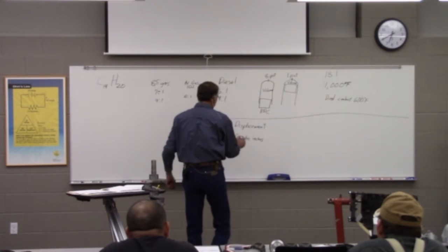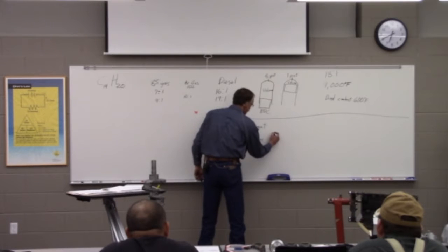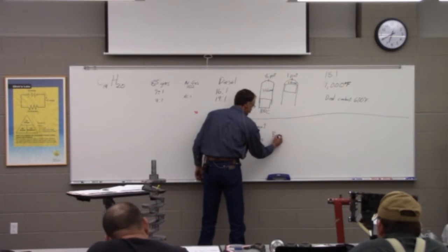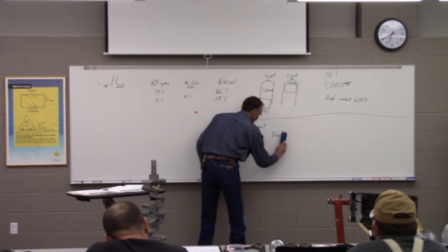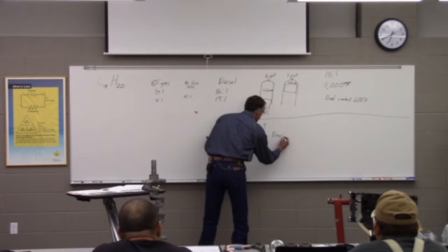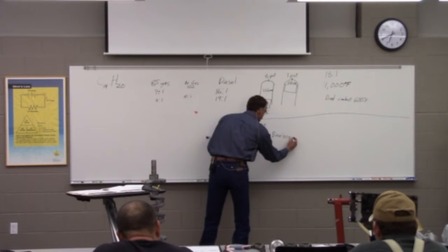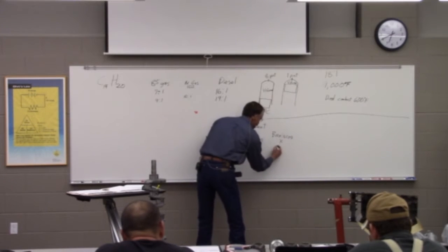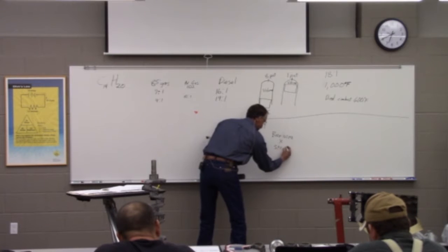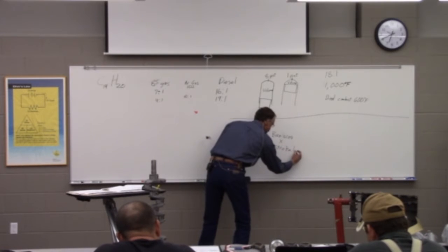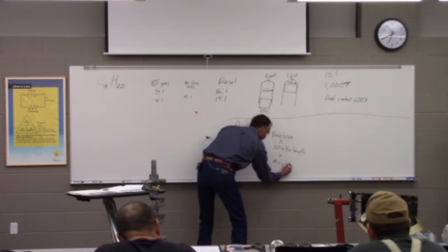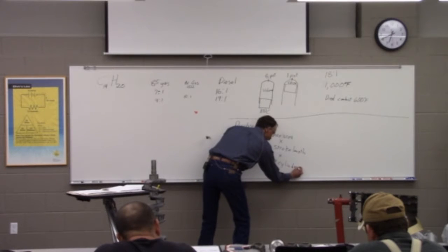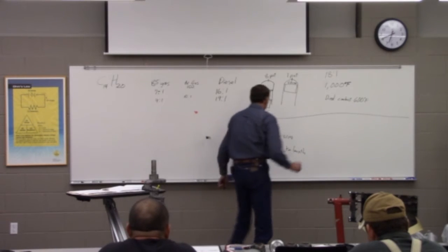So the displacement is the bore area, times the stroke length, times the number of cylinders. So we'll do one of those real quick.